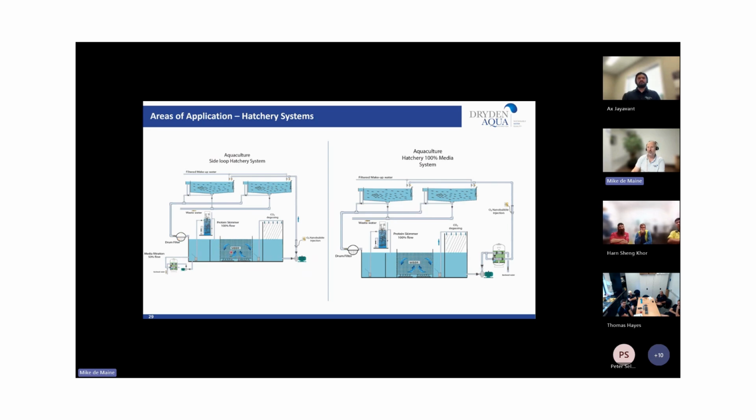The hatchery manager says that what he's finding is that the system with the drum filter is actually needing to backwash the AFM more often than the system without the drum filter. Why is that? Because quite often the plant operators are running the drum filters with too high pressure differentials, which means that the fine organics are being squeezed through the mesh of the drum filter.